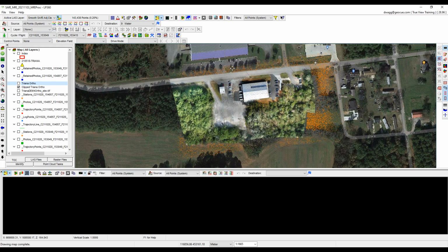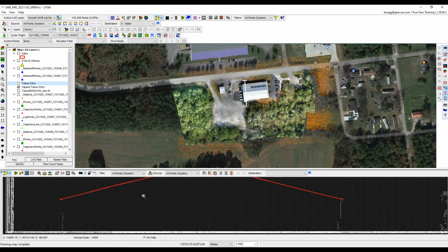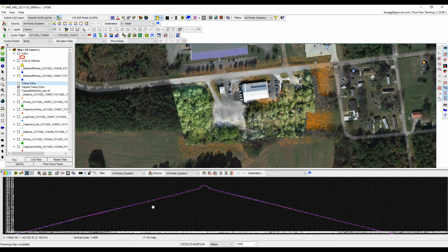Yes. So it's looking at the dynamic errors within your trajectory solution, and that's going to be both position and orientation. And so the majority of that's going to be elevation biases between flight lines, but there will also be things like horizontal adjustment that's coming from adjustments to the heading error within some of the data sets. And so you will see horizontal adjustments, you'll see better alignment of some of the features. This one didn't have a whole lot with it, but it did have some. You can see some better alignment when you looked at things like the roof line here.